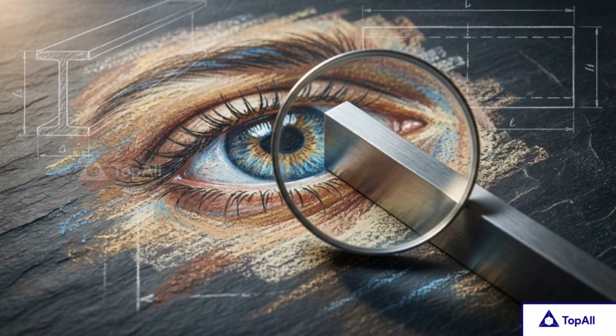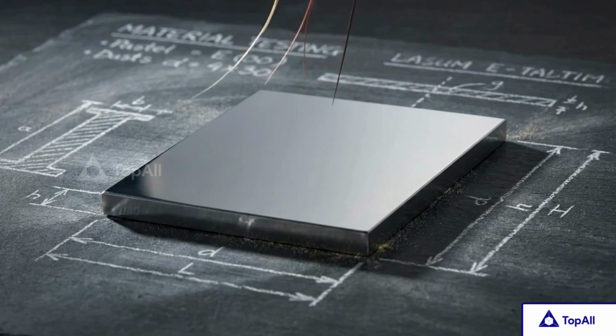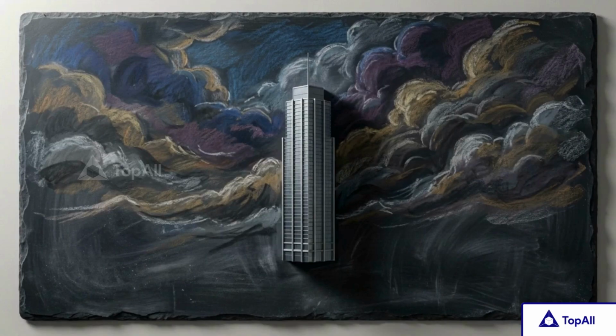The resulting calculation reveals a displacement that is nearly impossible to see with the naked eye. Under the sideways force of 90,000 newtons, the top edge of the slab moves by only 0.16 millimeters. Even with the horizontal force of 2 elephants, the metal block shifts by less than the thickness of a few human hairs. This resistance, dictated by the shear modulus, is the physical principle that allows solid matter to maintain its integrity under extreme loads.